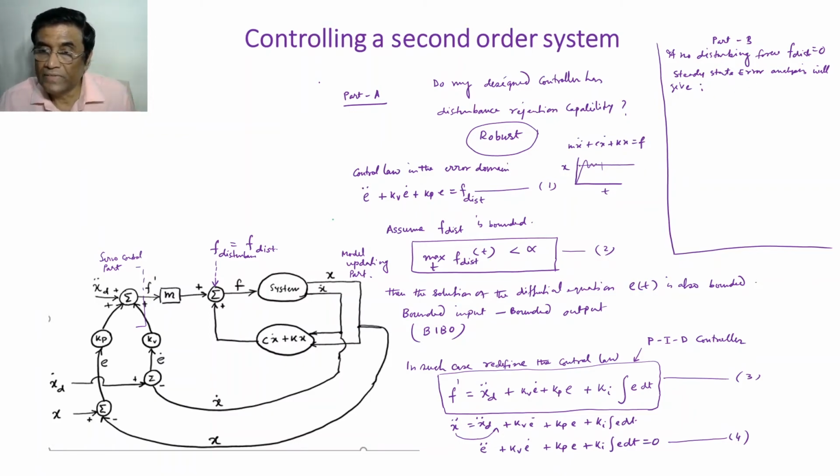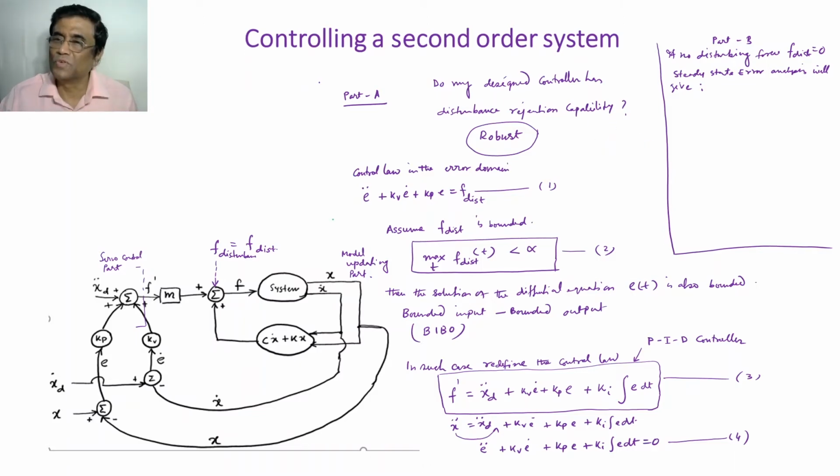And this is called the transient state, meaning there will be some error and response time depending on whether it is an under-damped, critically damped, or over-damped system. After some settling time, ideally in a good controller, there should not be any error, which is called steady state error 0. And this is analogous to a very, very crude example I am giving.